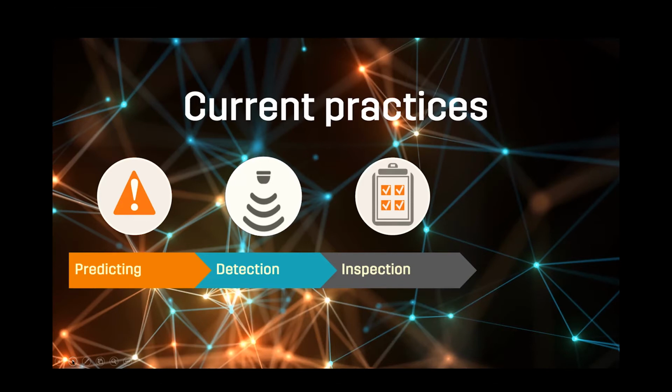Radiography, again, can be used effectively to manage and inspect CUI through the insulation. However, even with the progression in digital radiography, we still have some concerns within the industry due to the radioactive sources and the HSE risks associated with it. But radiography is a good alternative, though again, we need to try and make it a safer option as we move forward.